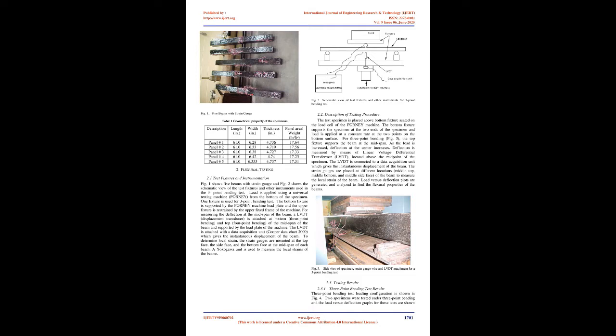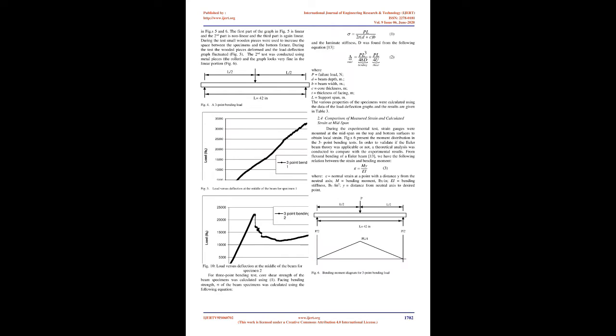The static and flexural fatigue characteristics of foam-cored polymer composite sandwich beams are investigated by Shenoi et al. [7]. The skins of the beams are made from hybrid glass-aramid fibers set in epoxy resin, and the core materials are linear and cross-linked polymer foams. The applied load in a 10-point configuration approximates a uniformly distributed load throughout the span of the beam, which is simply supported at the ends. The testing frequencies are 0.33 to 0.91 Hz.